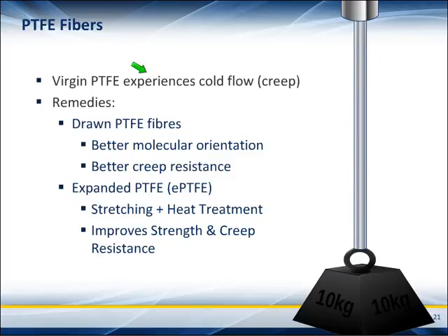And this happens when you put a gasket made of PTFE between flanges. It starts to cold flow and loses the stress on the flanges. As well, if you put pure PTFE into a stuffing box, it starts to lose volume. It starts to extrude very, very slowly because it suffers from this cold flow problem.